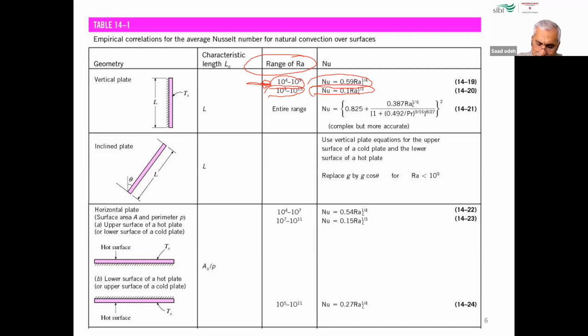It's quite complicated, but it will also give you the correct Nusselt number. But in the final exam, I don't recommend you do this because, as you can see, it has a mathematical process, and you might make mistakes with the powers, brackets and divisions. So refer to the first two, which are more convenient, but you need to find the Rayleigh number first in order to choose which one is correct.